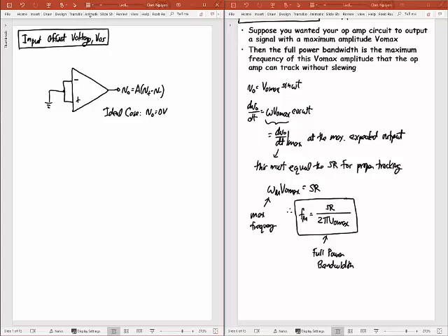So if you go in your lab and you ground out both of the plus and minus terminals of that actual op-amp, you expect that output to be 0. Has anyone done that in lab yet? Okay, what happened? It's not 0. Yeah, so the reality is that V0 is not 0. And what did you measure? About 0.67. Really? 0.67 millivolts? Oh no, you're already telling me with the offset voltage. I mean, what's the output voltage?